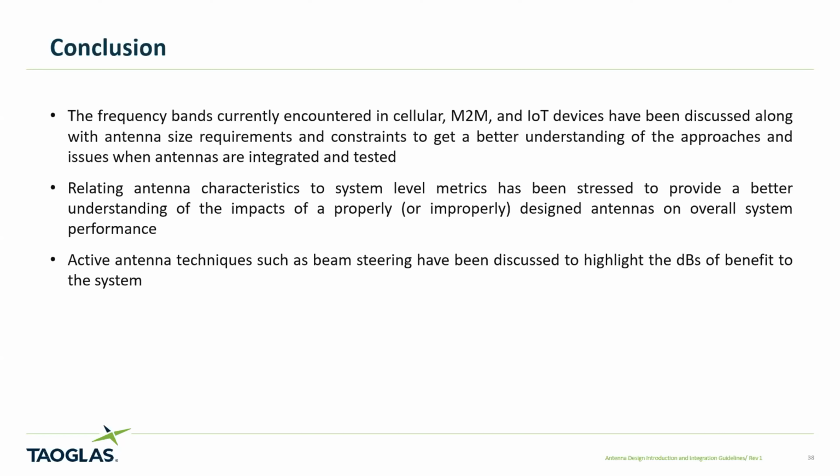For millimeter wave, the way I think they're going to run on a client device, say the smartphone, it's going to be 4-element arrays. So they're going to have a certain EIRP. It's not going to be very robust, but back on the node, they're looking at 64, 128, 256 elements. So they can drive the gain up on the node to that 22 to 30 dBi gain level. You can get a very high gain on the node in a very small area because of the small size of the antennas, to support a high EIRP.